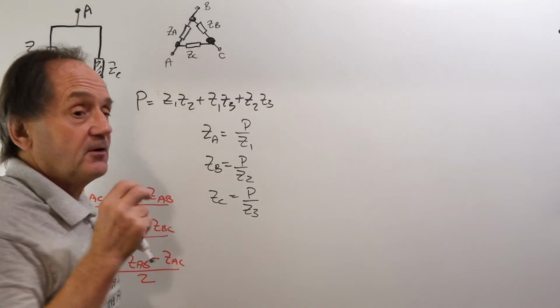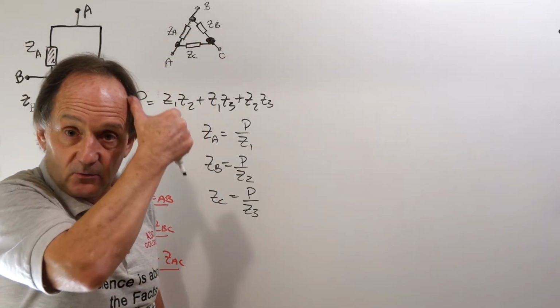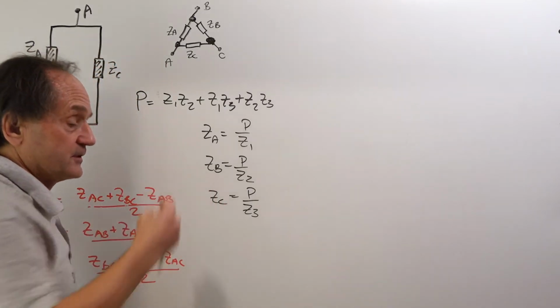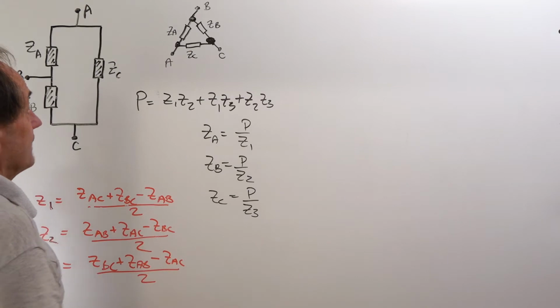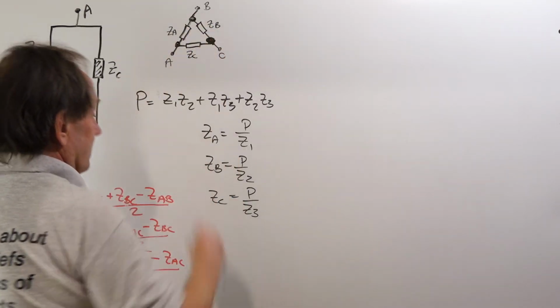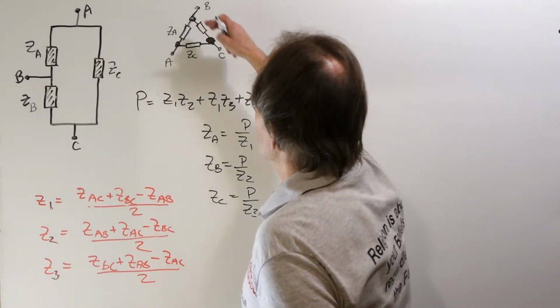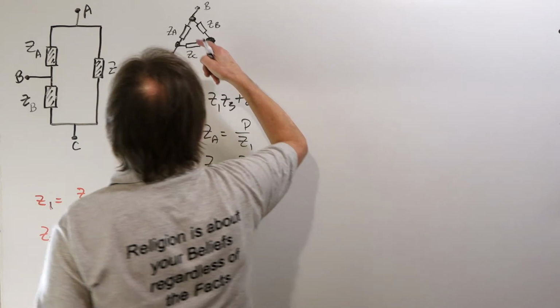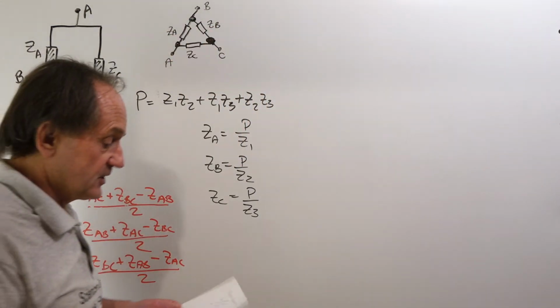I had to put them very close together so that they'd be in thermal proximity to keep them stable temperature-wise, and also to reduce lead length errors. So my only option was to measure the impedance between the various nodes and then compute what the individual resistor values were to see if they had shifted.